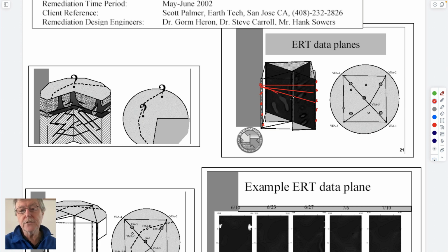So just like a medical X-ray where you use electromagnetic radiation, you're just measuring the electrical conductivity between them. And once you have the electrical resistivity measured between all of these points by doing all of them in sequence to go across, so you have a complete network of this, you invert all these data to be able to say piecewise within here what individual block electrical resistivity is. So you have a color map, if you like, of the electrical resistivity.